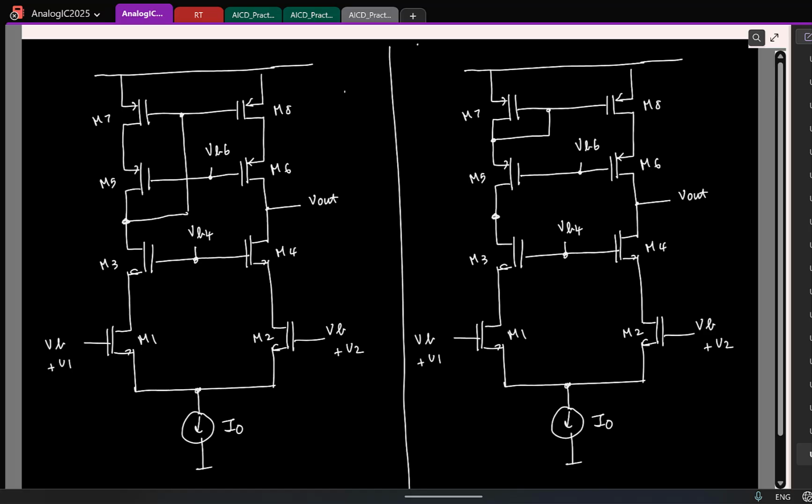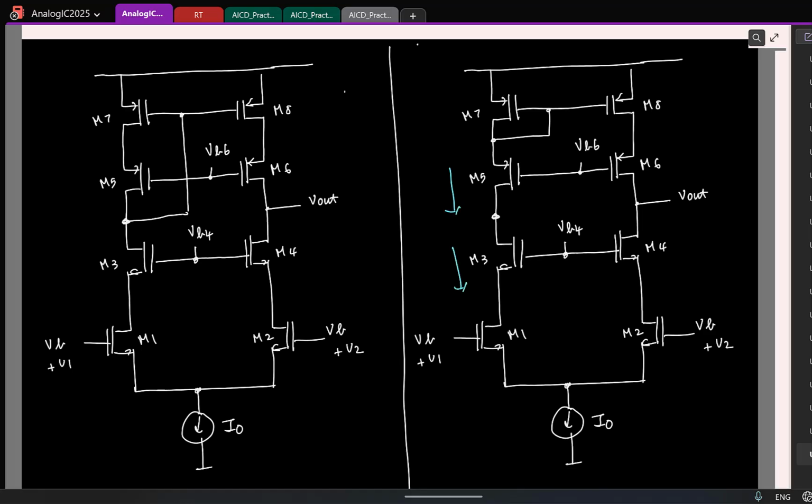Now I know that the PMOS current source current is set. So I can look at these two currents, and then I can basically go and do this to bias my M5, M6 also. You can think about it and argue, the same argument holds good.